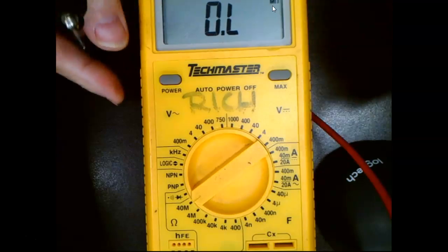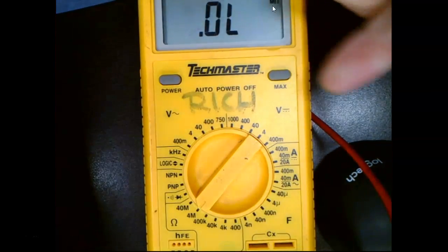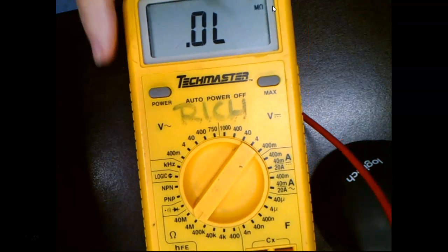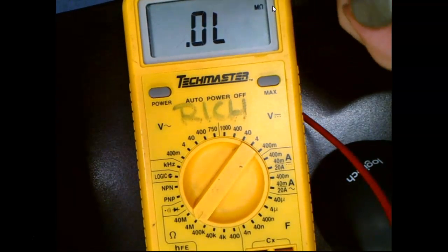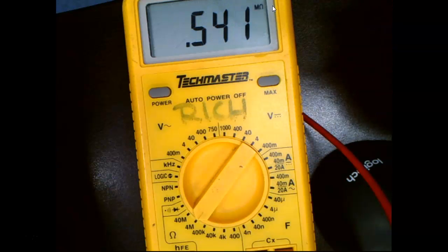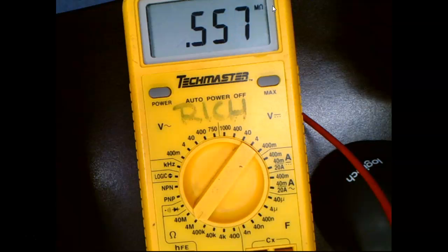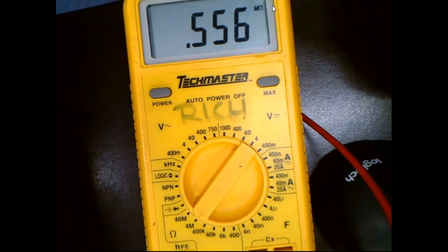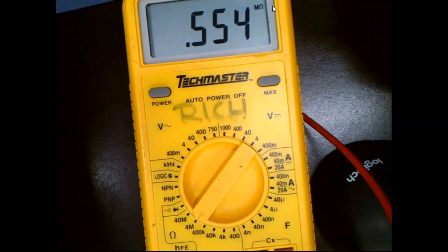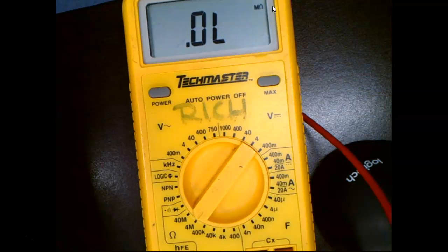So this one, I've got it on ohms, I think. I think I've got it on the 4 meg scale. So this is about 540K, right? And this is what people do. They'll write down 550K, 0.55K, and that's improper engineering notation. Meters do not range that way, because we have either a 2,000 count meter, which is going to range on 199. It's going to range on twos, right? No matter what they are.